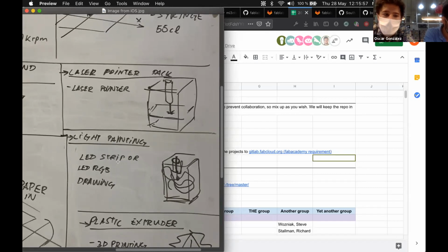The only thing here is that if you want to use NeoPixels, Edu, you were saying that you cannot use them with GRBL? No, GRBL doesn't support NeoPixels, so you will need to take Marlin, which is from 3D printers, and modify it to match this PCB, because Marlin supports NeoPixels, but GRBL does not. Or make your own software to control it based on positions.